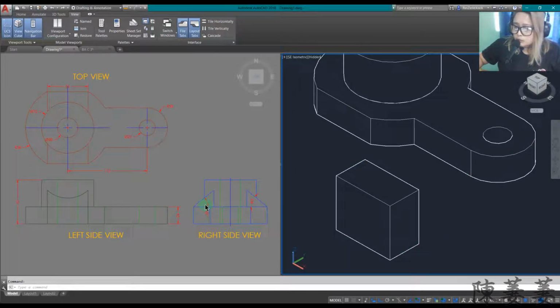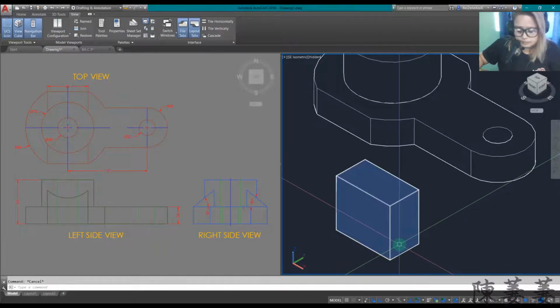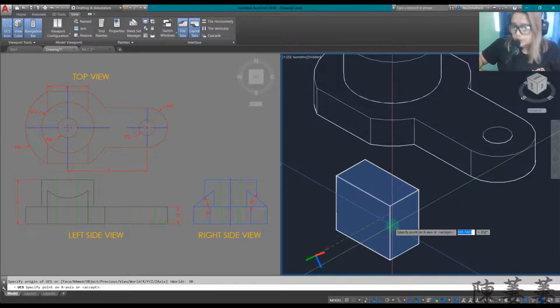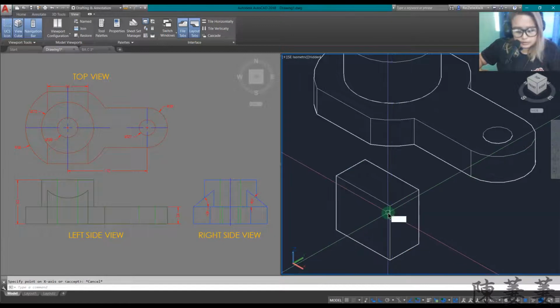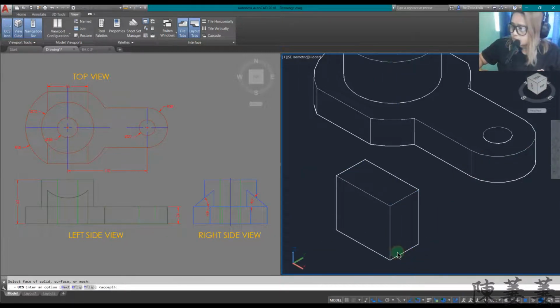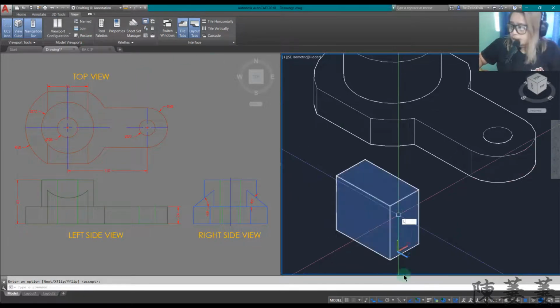We're now going to modify the UCS so we can create this angle where we can use to press or pull the excess. UCS 3 points. Or you can use UCS face. Line.